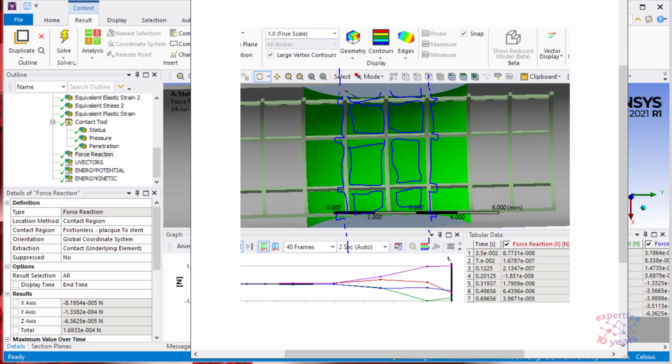If we hatch now to obtain the proper contact area between the stent and the plaque, the area of the hatched surface, in reality the area of the small struts that come into contact, can be used in the formula for pressure or stress: force over area.